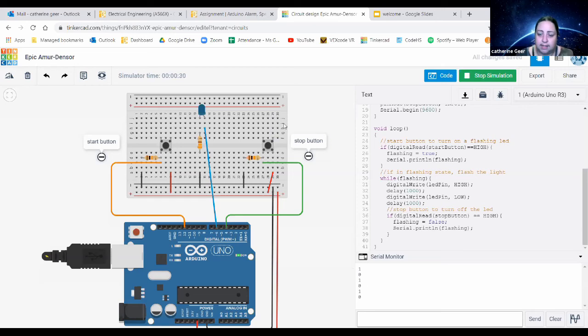And the reason for that is that your program is executing each line one at a time. So it is going to turn on the LED, wait for 1 second, turn off the LED, wait for 1 second, and then check the button. So if you clicked the button in here, say halfway through this first second, it's not looking right now, okay? And that's just the way Arduinos are. So I need you to be okay with that and embrace it. It is executing 1 line at a time in order.